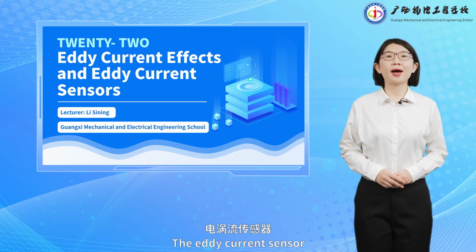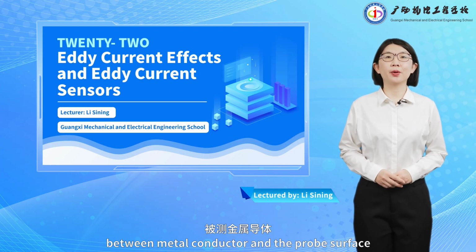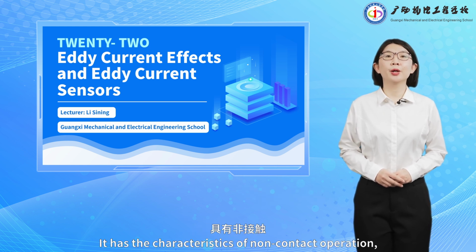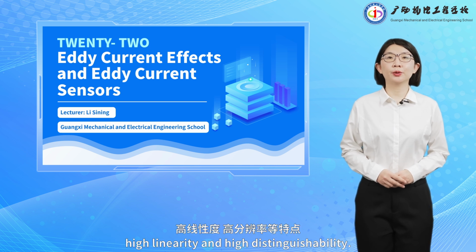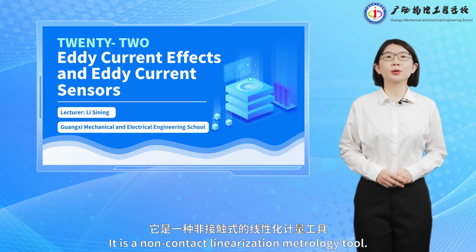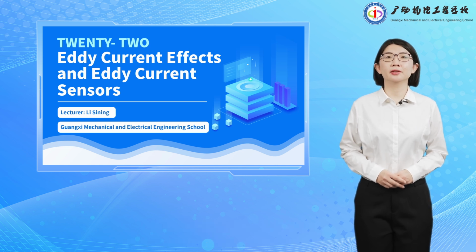The eddy current sensor can measure the distance between a metal conductor and the probe surface statically and dynamically. It has the characteristics of non-contact operation, high linearity, and high distinguishability. It is a non-contact linearization metrology tool.